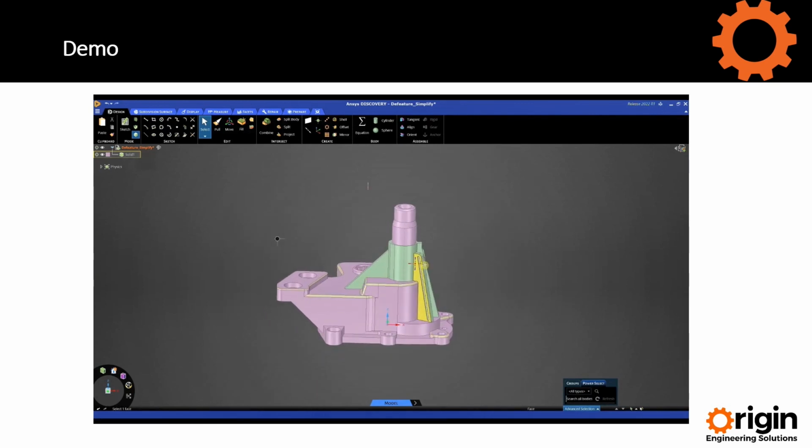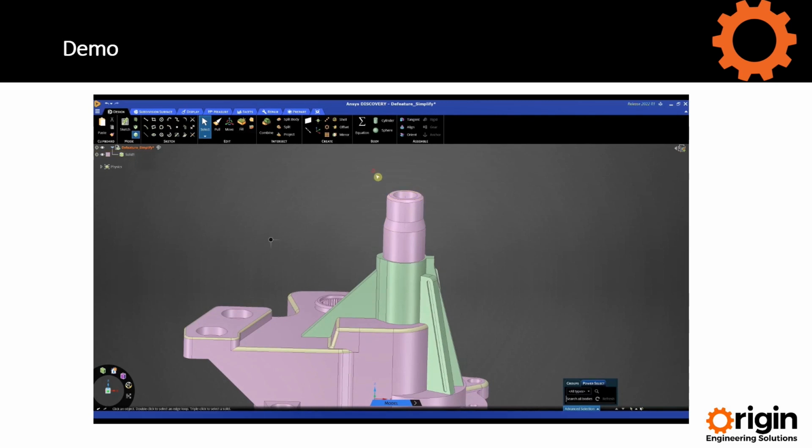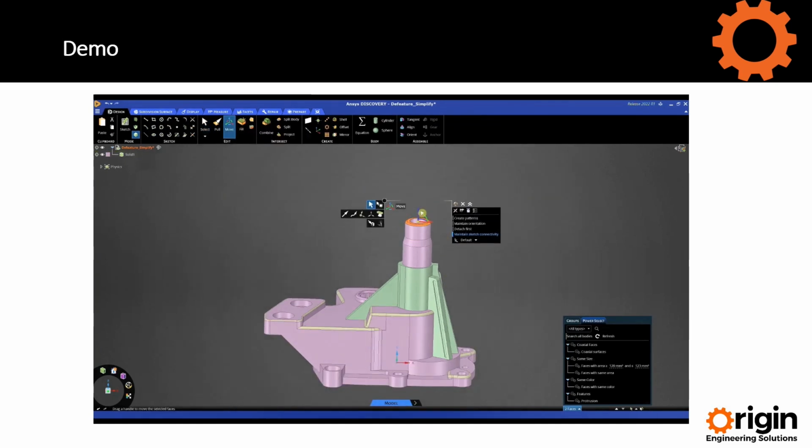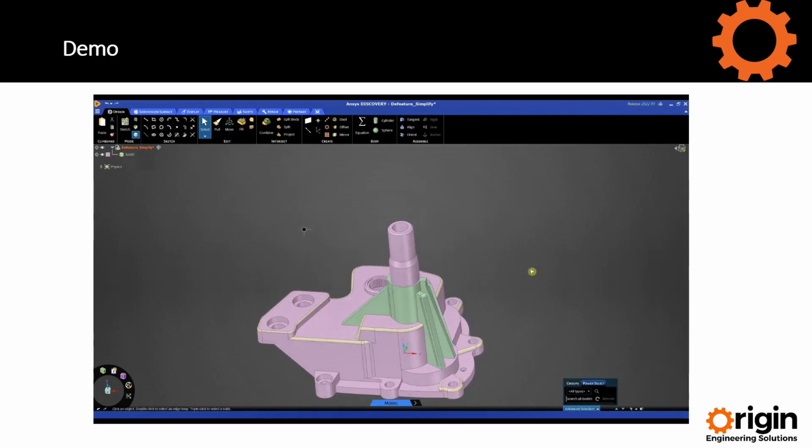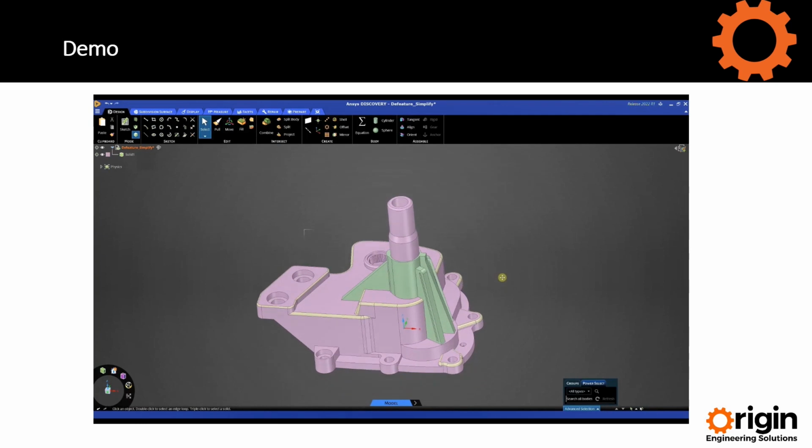So if you run a simulation on this, a structural one, and you find that maybe you need to make a quick change, maybe I need to change the height of this area here, I can use my move tool very quickly, increase the size of this to suit, and I can maybe make another variation and the model's slightly higher. So we're just making those quick design changes, and all this is possible in Ansys Discovery.